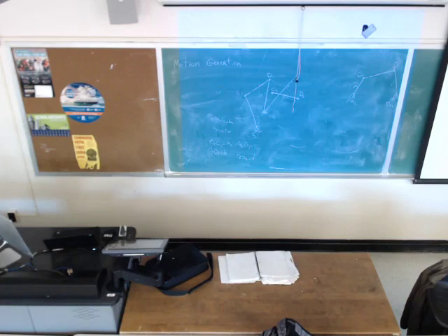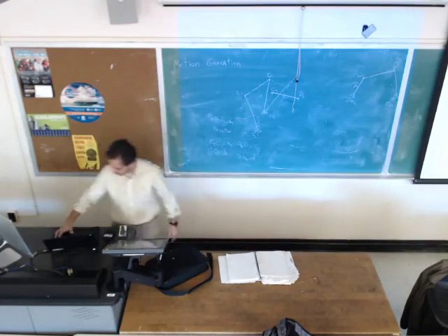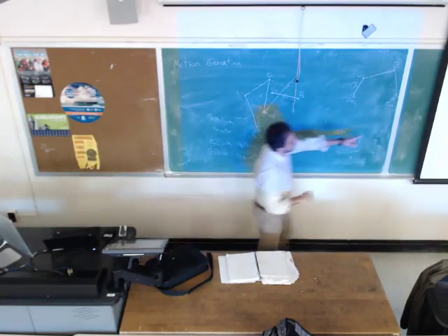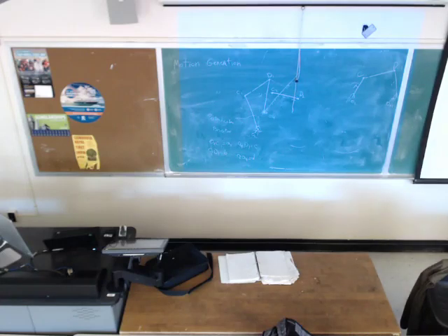So you are talking about the shape. The shape doesn't matter how it's going to look. I just showed you on the previous slide. If I want to connect here, if I have a binary link from this joint to this joint, it can be straight, or it can have any other shape. What is important is it has 2 nodes, which it has been connected to the other link. So this is the ternary because it has 3 joints.